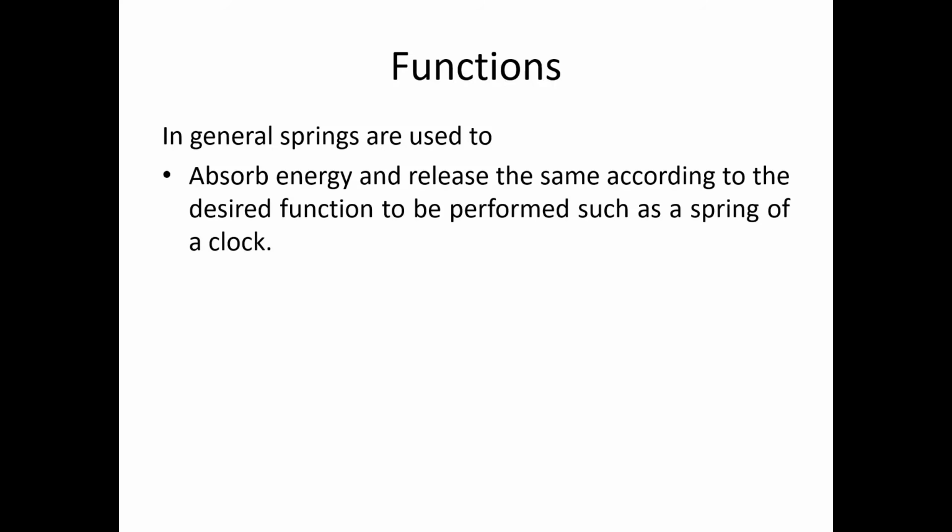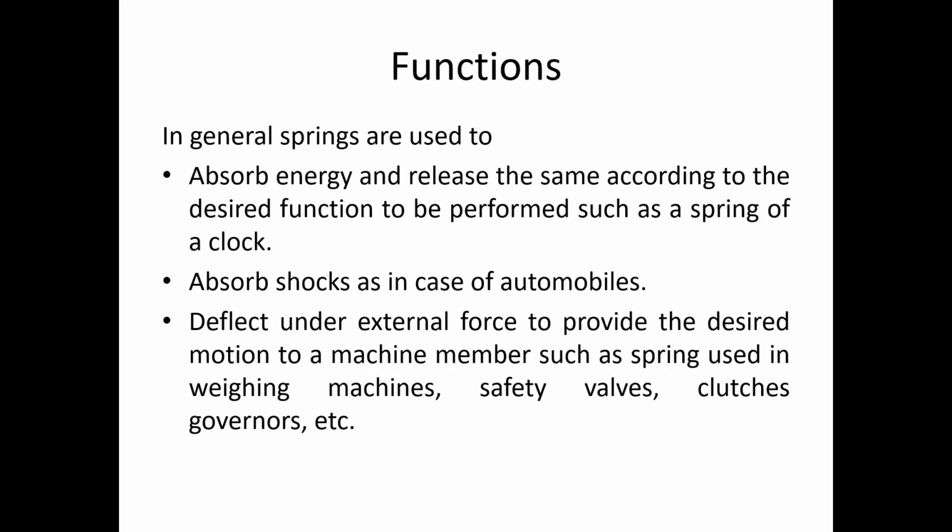Now let's have a look at the function of spring. In general, springs are used to absorb energy and release the same according to the desired function to be performed. For example, the spring of a clock. It also absorbs shock, for example, springs used in automobiles. It also deflects under external force to provide the desired motion to a machine member, such as springs used in weighing machines, safety valves, clutch, governor, etc.